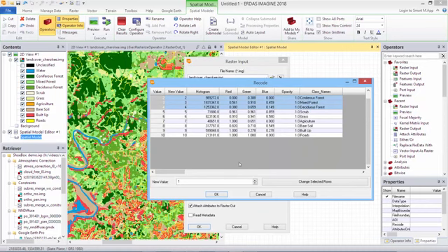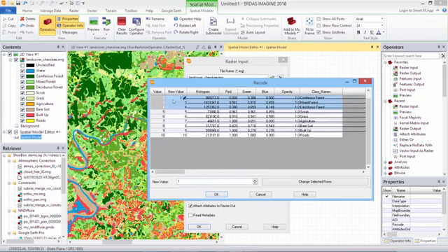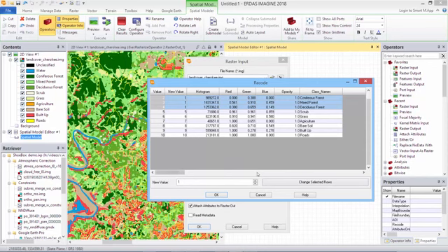We're going to go ahead and change those to class 1, so the new value field is already set to 1. You can see the new value column here. We're going to say change selected rows, and that updates their new value to 1. Actually, I'm going to change that to 2 at the moment. I'll show you why in a second.